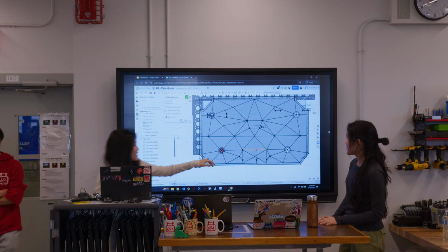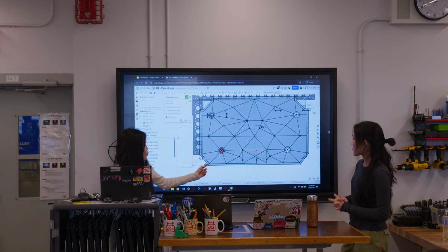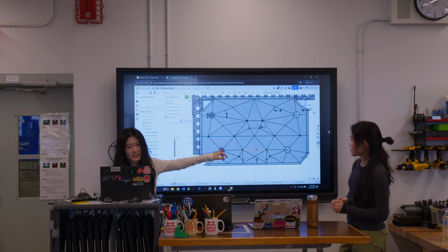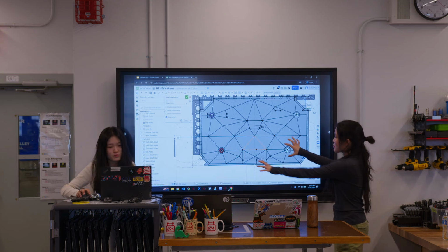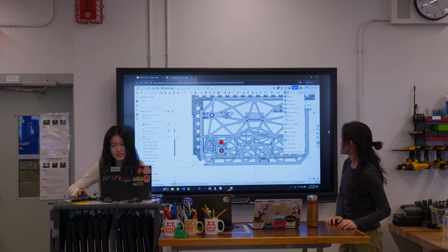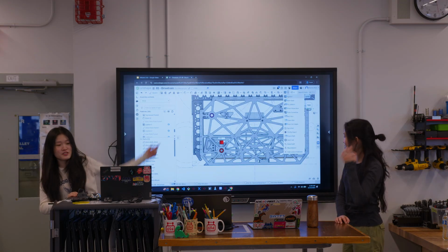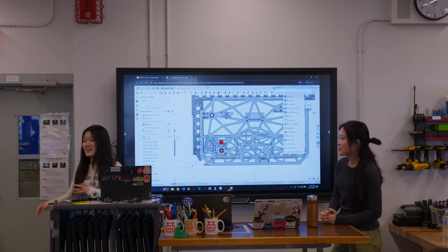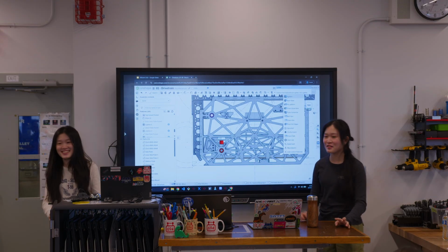But most of the time we'll make lines that go to where the force will be concentrated. Like in the drivetrain, the wheels will be spinning, so that's where there'll be a lot of force. So we map it out, and then we use the Lighten tool. You guys can just search it up. It's a FeatureScript, and we just click on these parts and then it automatically does it. But sometimes manual pocketing is useful.